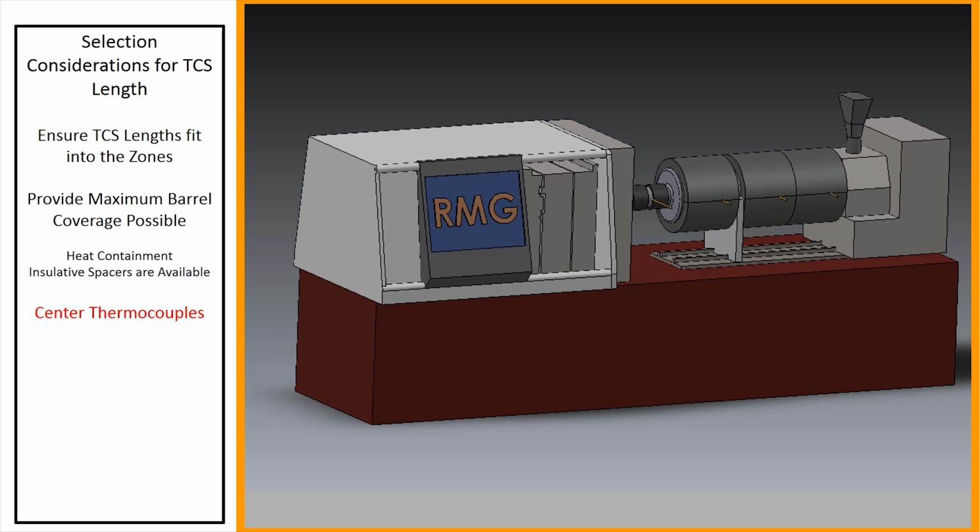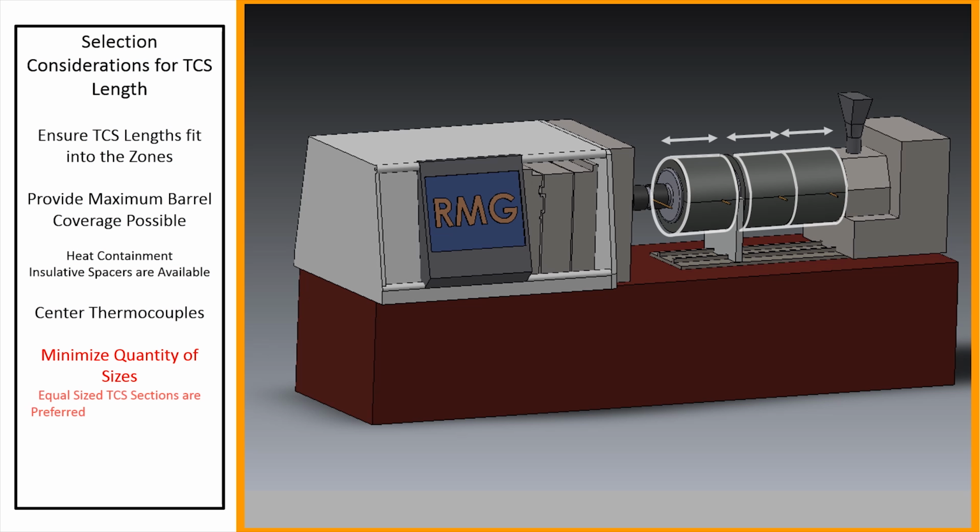Next, effort should be made to generally center the thermocouple on the TCS section, since the thermocouple is the controlling entity for the heater. It is also best to minimize the quantity of TCS sizes. Equal sized TCS sections are preferred over using several varied sizes.